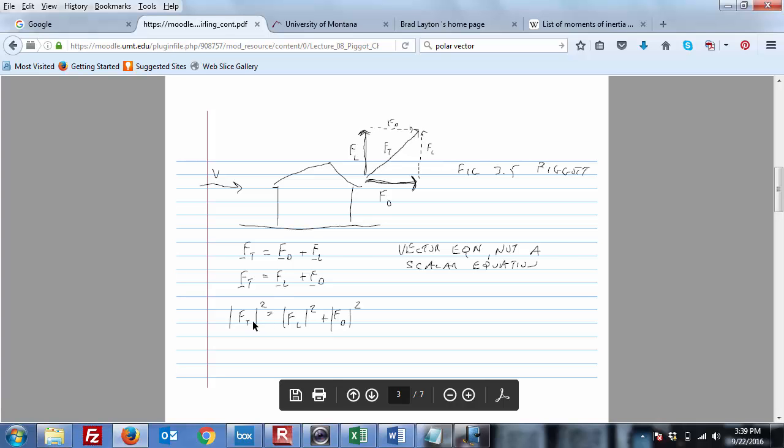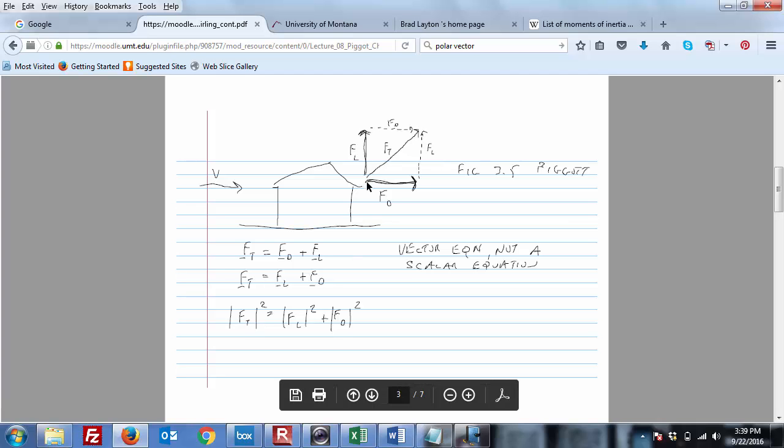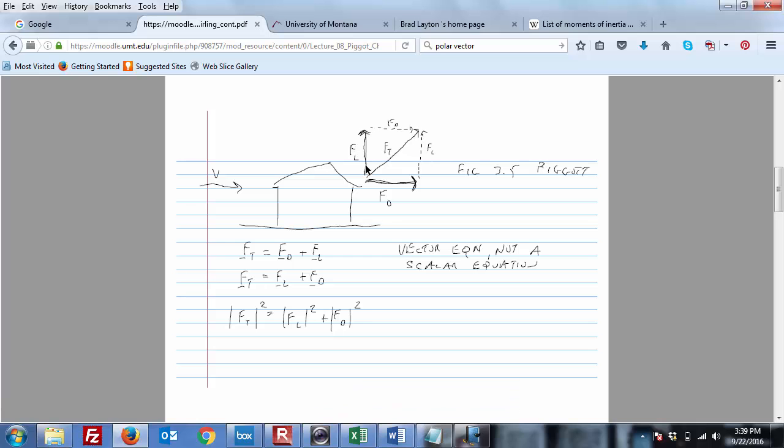So there it is. Now, why is this important for wind? Well, you've got two types of turbines. You've got Savonius and Darrieus turbines. Savonius work on drag. It gets pushed along, and you've got Darrieus, which work on lift. It gets pulled along.